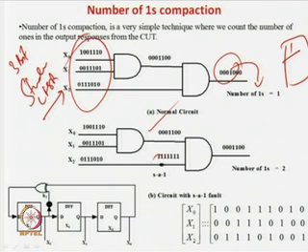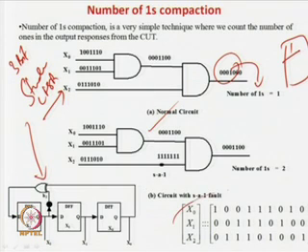Now, let us consider a stuck-at-1 fault over here. A stuck-at-1 fault will make all these cases all ones, like if this is one vector, this one vector, this one vector and so forth. Seven vectors were applied because all zeros cannot be applied. So, this is our standard LFSR which we are using. This was the characteristic polynomial, already we have seen that.